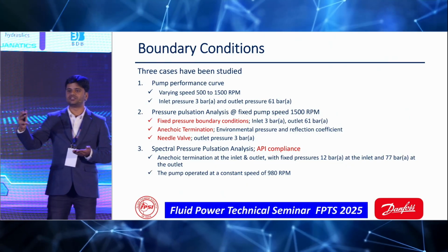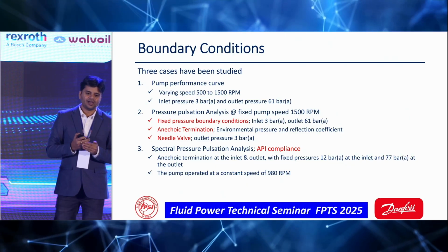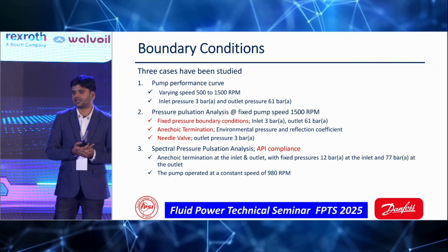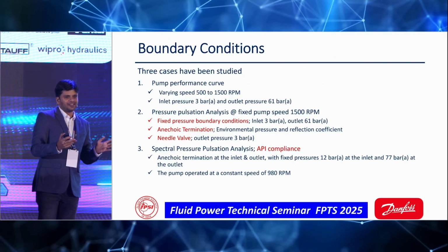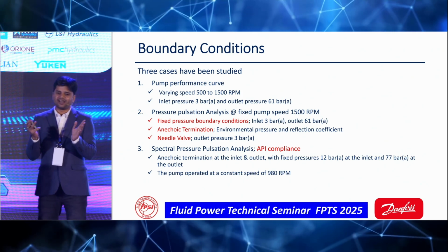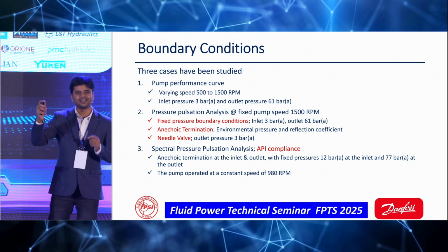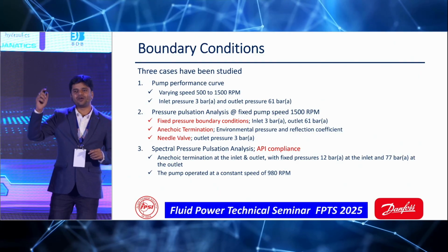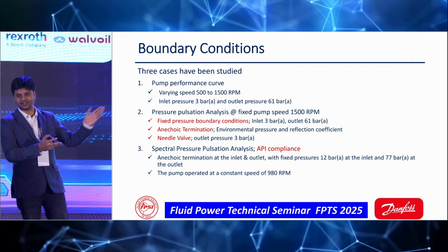And the second case is for the fluid dynamics engineer. Now I said that there are pressure pulsation waves; they act just like sound pressure waves, right? How do we model these mathematically? There are three things we tried. One is, just like a beginner in computational fluid dynamics, if your boss asks you to simulate, you basically set inlet pressure as a constant 3 bar and outlet pressure as 60 bar. But you can see the result of it in the next slide.